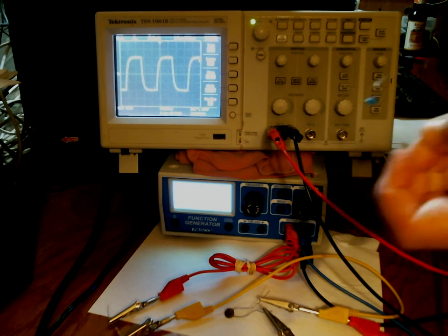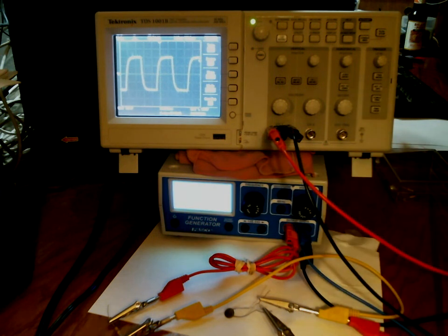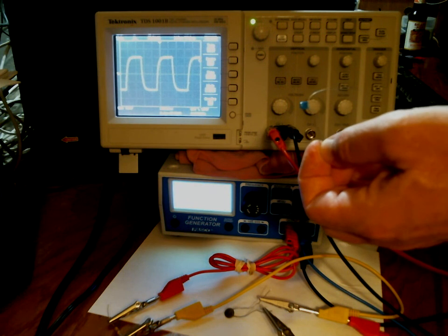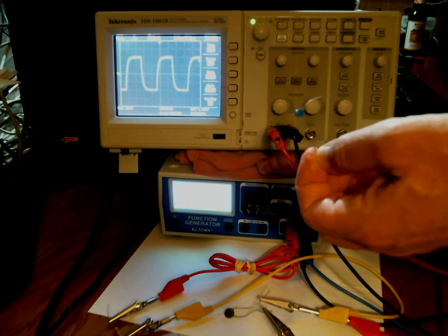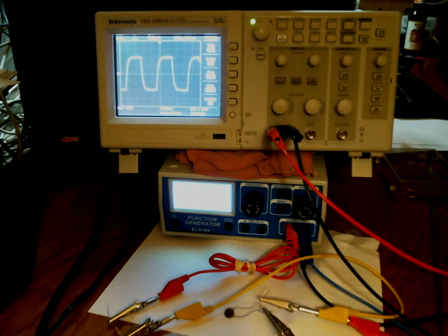Now I'm ready to swap in the unknown capacitor here, and I've got the known capacitor there on the scope. I want you to think for a second about what we would expect to happen if we put in a different value of capacitor. So there are two possibilities. The unknown capacitor could be either a higher value or a lower value than the known. Let's say, for the sake of argument, that it's going to be a higher value. If it's a higher value, I want you to pause the video and think about how you would expect that trace to change for a higher value of capacitance.